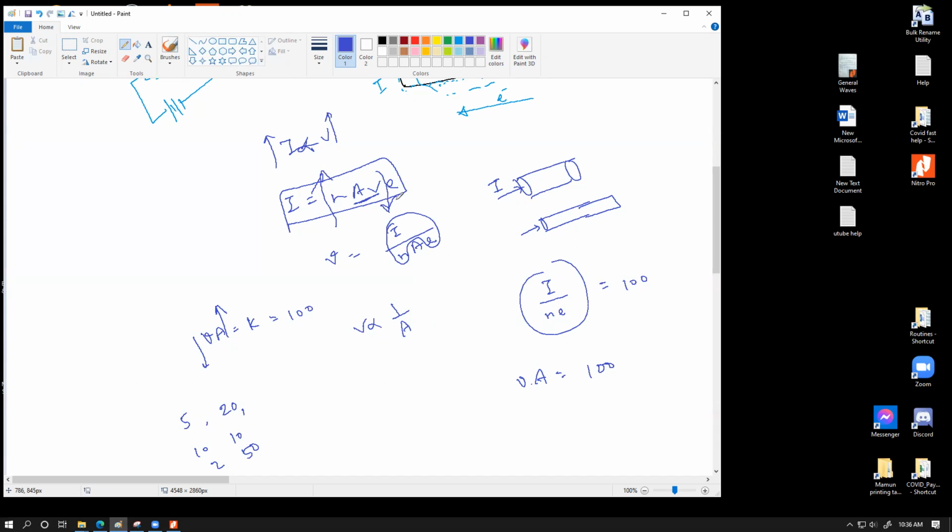When temperature goes up, more valence electrons from a semiconductor's outer shell can reach the conduction band. So with the increase of temperature, a semiconductor piece experiences a significant increase in its n value. As n goes up, I also goes up, which essentially means R has gone down.